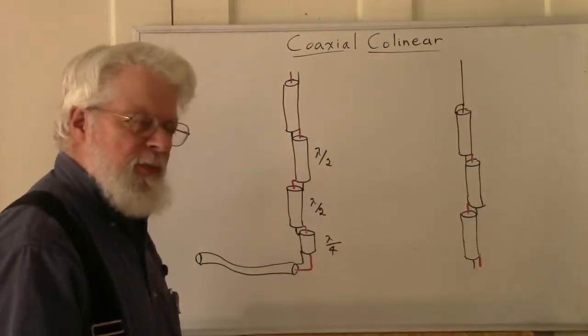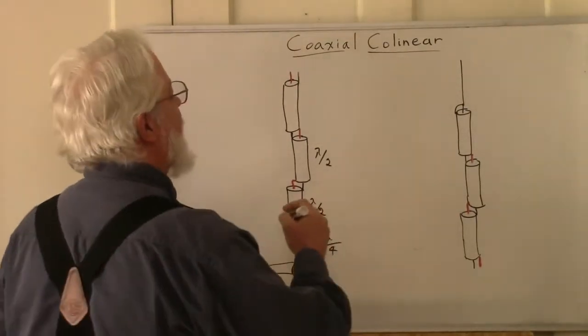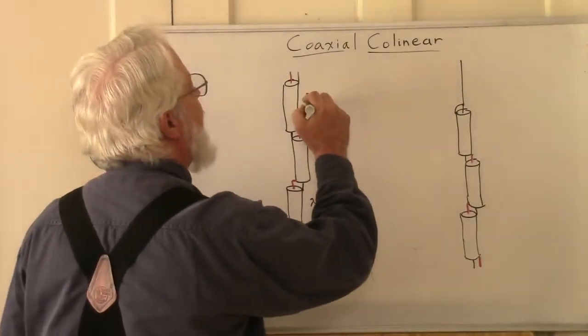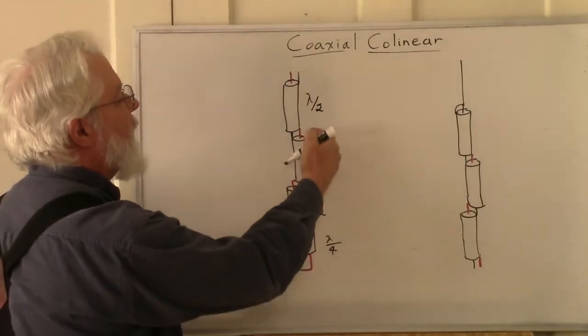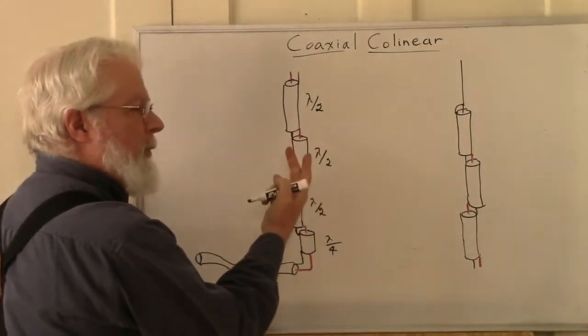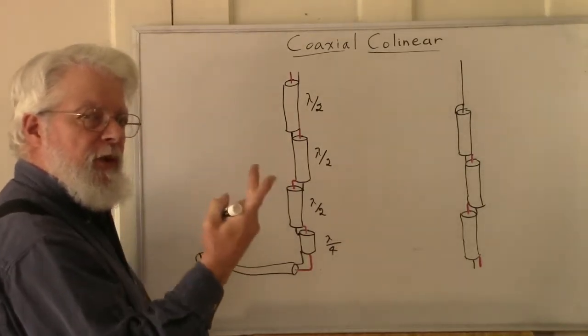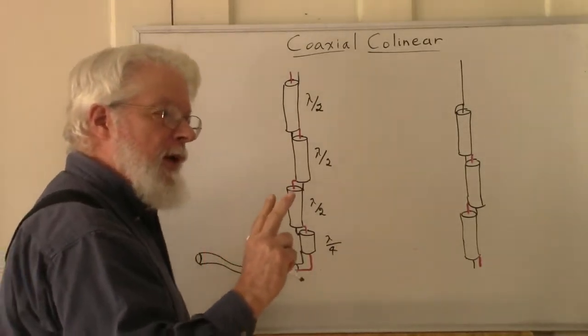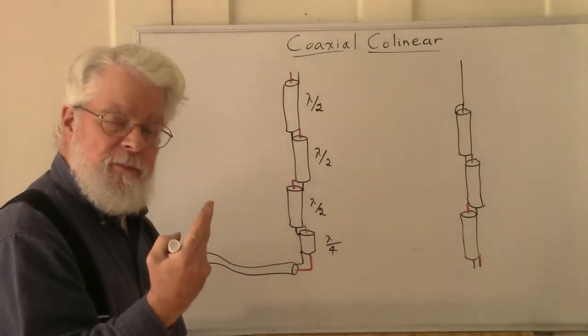I think there's a point of diminishing returns though. 9 dB is probably that point. And finally we have another half wave section. And each time we transition from one half wave to the next, we flip our feed. The center conductor becomes the shield becomes the center conductor. And by doing that, we achieve a 180 degrees phase shift.